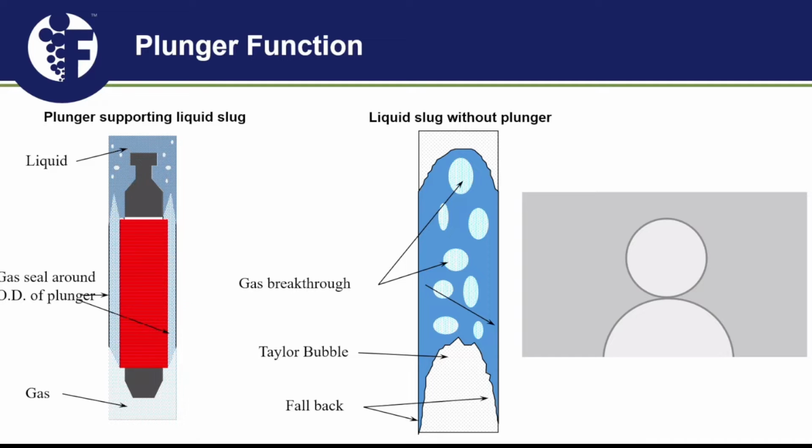So, here's just a little schematic, right? When we talk about plunger lift, or really just any kind of production, if we look at it from a natural flow standpoint, this is typically what we see. This is a slug flow regime. We may also see an annular mist flow regime, and it basically just defines your fluid and gas characteristics throughout the wellbore. When you're in either slug flow, as depicted in this picture, or annular mist, you get a lot of liquid holdup and fallback, right?